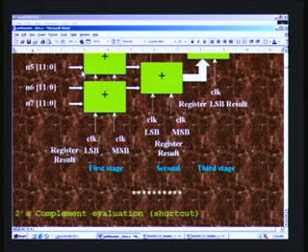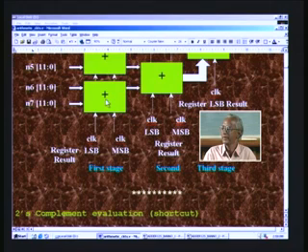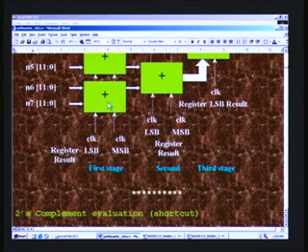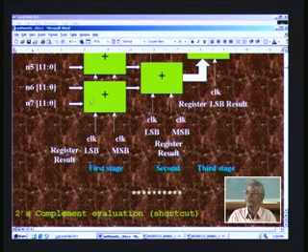So you see that every function is divided, and LSB, MSB are basically performing that add operation, and in this case all of them are add, so you won't know the functionality partitioning, although functionality partitioning is also implied here. So LSB, MSB is treated inside, whereas for the actual functioning we can treat it as this is one adder, this is another adder, and so on. So that is how different functionality is also partitioned. Therefore this particular design has partitioning of not only data width but also the functionality.